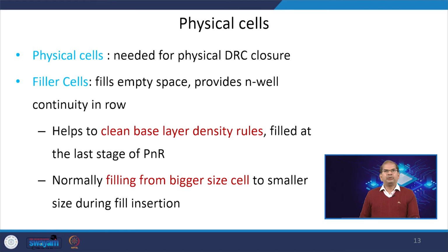Now, we have different physical cells. The physical cells are needed for DRC closure. If you can see the filler cells, the filler cells are used to fill the empty space and provide continuity of n wells.